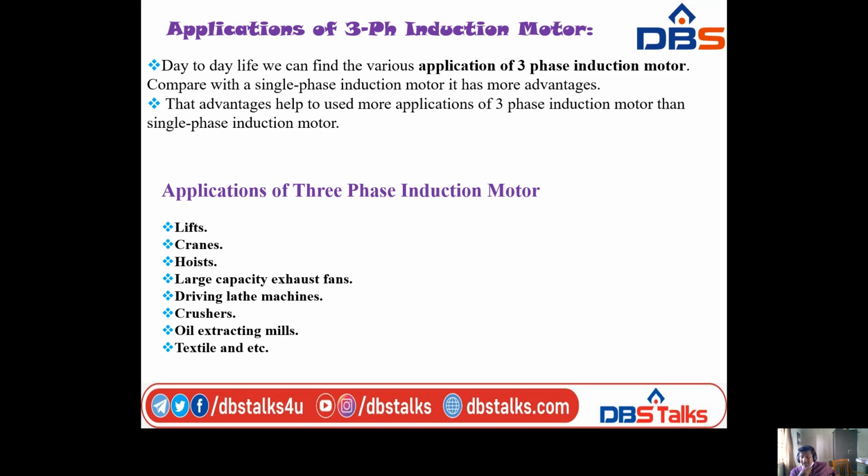Generally, the three-phase induction motor is also called a self-starting machine and also called an asynchronous machine. Asynchronous means it does not run at 1500 RPM, it does not run at synchronous speed. That's why the three-phase induction motor is also called an asynchronous motor. The induction motor is always running below synchronous speed, that means below 1500 RPM. So it is always running at asynchronous speed, and that's why you can also call it an asynchronous motor.